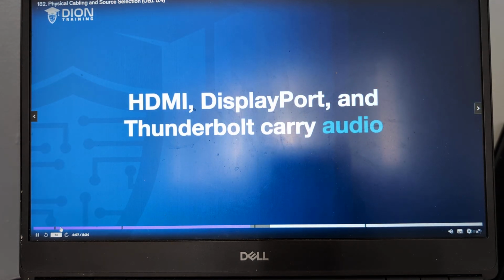Now, it's also important to remember that when you're dealing with a lot of these digital standards like HDMI, DisplayPort, and Thunderbolt, they can also carry audio over that same cable. So if the end user is having issues hearing the sound from the system, it could be an issue with that cable as well, and this would be another case where you'd want to replace the cable with a known good cable and see if this fixes the issue.